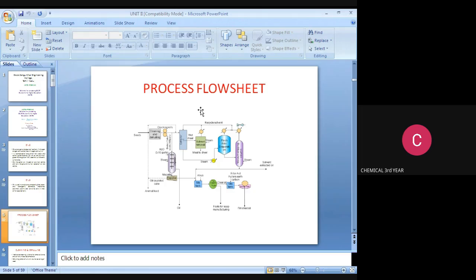We are recovering it and it goes to the expeller, where the oil is removed, and the oil-depleted cake is passed to another tank and used for animal feed. The top layer of oil is extracted and passed to the extractor. Here the meal is extracted using solvent. That solvent is recovered and then it passes to flash film evaporation. The evaporation takes place and then it passes to the vacuum stripping column. In this stripping column we add steam and then it passes to the alkali tank. In this alkali mixing tank we add alkali and then it passes to the centrifuge. In the centrifuge we remove the foots, used for soap manufacturing, at the bottom.